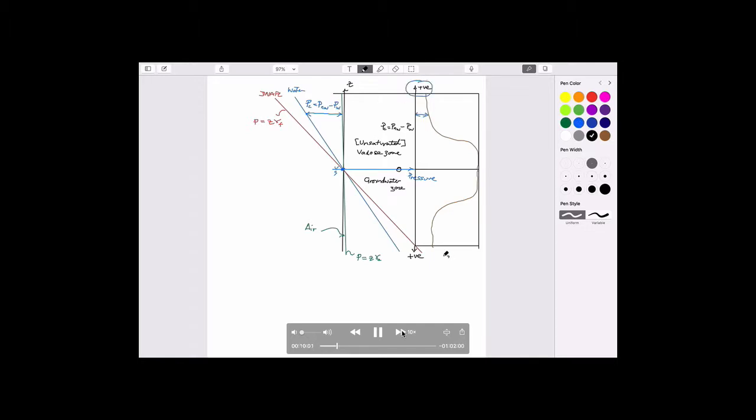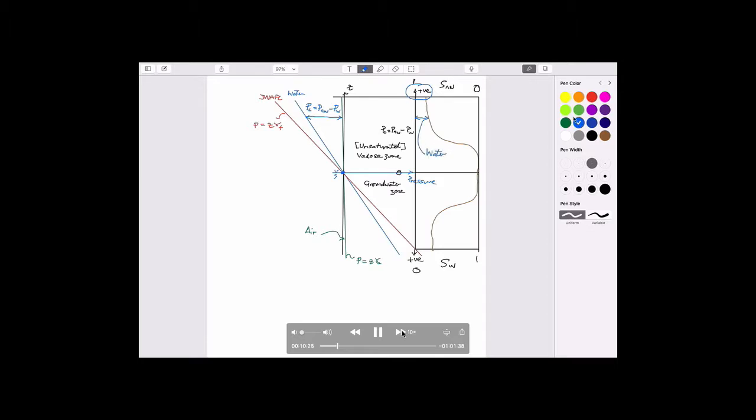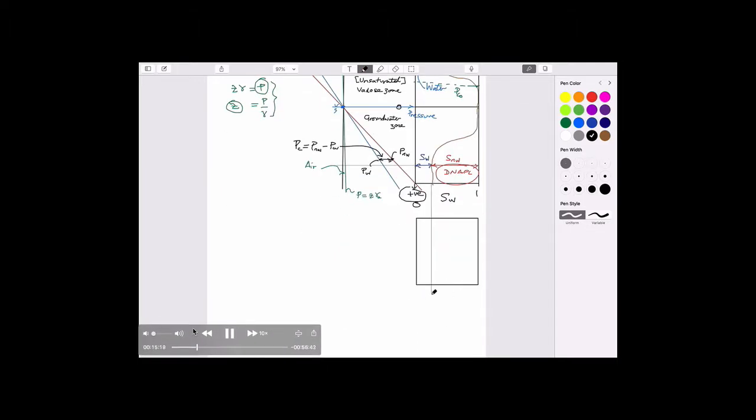And they're characteristic, but they're flipped. One's the mirror image of the other one. And they really define how the saturation changes from at the water table to be quite high saturation of water and a reduced saturation of water as you go up to the ground surface. And below that, below the water table, a high saturation of water close to the water table and a reduced saturation as you get deeper because the DNAPL can penetrate. And so we rationalized everything that we can do based on those capillary pressure versus saturation curves. So those are key understandings for us.